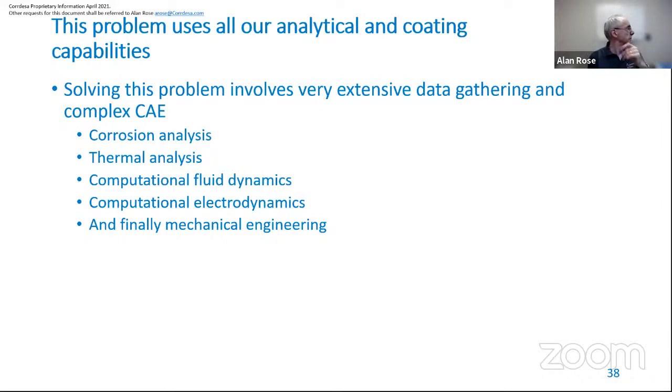Okay. The second question: what kind of PPE do you need to do brush plating? Well, generally, go ahead, Alan. Okay, yeah. With the PPE, there's a good point here. With the Dualistic, if you recall, we have electrolyte being supplied to that porous pad, and then we have a second pump in this whole unit that sucks back the excess electrolyte at a much higher volume rate, because it also sucks back ambient air.